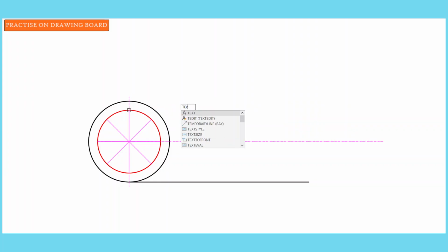In this case, you'd have to use your 45-degree set square. And once that is done, you can go ahead and label the divisional points. Starting from point P, we go to 1, 2, 3, 4, 5, 6, 7, and then 8 is P.